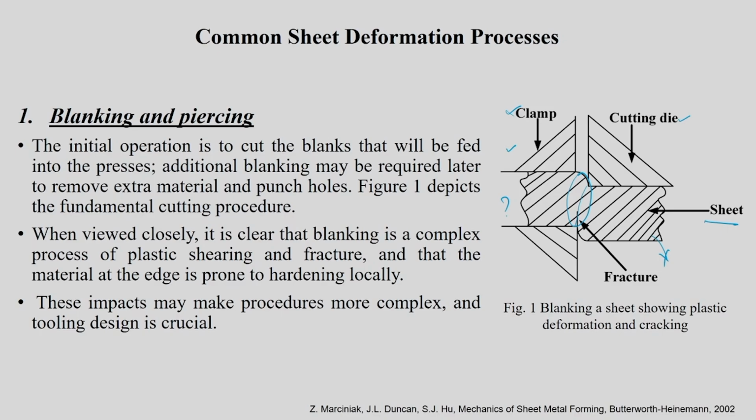If you closely look at this, it is actually a complex process of plastic shearing and fracture. You need to have plastic deformation in this clearance region. This clearance is also very important in this case, and this parameter, clearance, is generally designed in such a way that appropriate cutting is done. You will see that this edge region, that means the region which is undergoing deformation, will undergo localized hardening. That is very important, and this shearing as such is not going to make a shaped component, rather it is helpful for sizing.